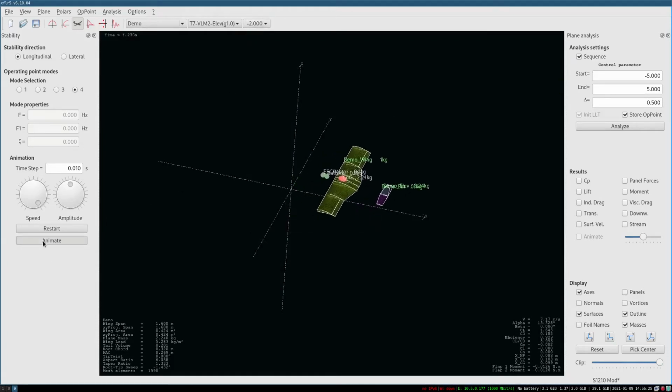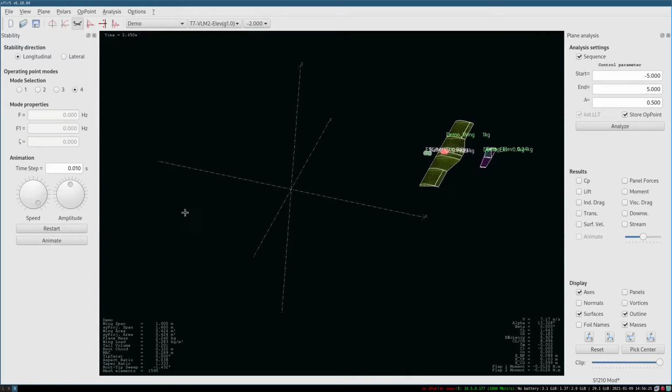So, for example, a gust of wind or anything that induces side slip will typically, you can actually see it happening here, result in a loss of lift, which leads the aircraft nose to pitch down with a slight roll angle, which means that as it speeds up, it will start to pitch up again, and it basically starts to initiate a turn like you would on a bank and yank, two-channel aircraft. This process is continuous, and it basically forms a big spiral until either someone acts to correct this behavior, or you run out of altitude.